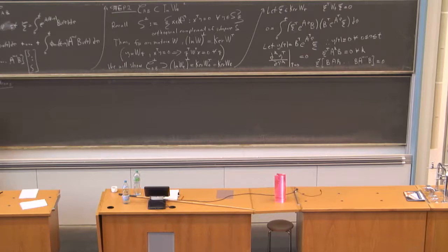I first have to rotate my vehicle. So if it's in this orientation, I need a rotation matrix that characterizes how I've rotated it to this specific orientation. That's just a rotation matrix. And I multiply that by the only net force that this thing can produce, which is just a thrust along here. So I basically have 0, 0, A. But of course, I have gravity to contend with, minus g. Okay? So that's the translational motion. Very straightforward to write down.